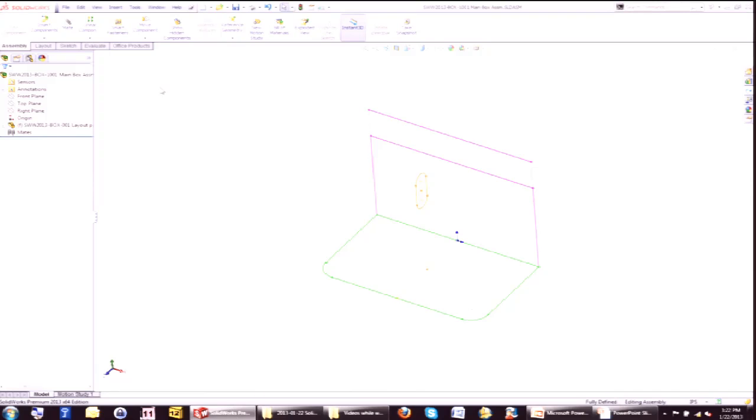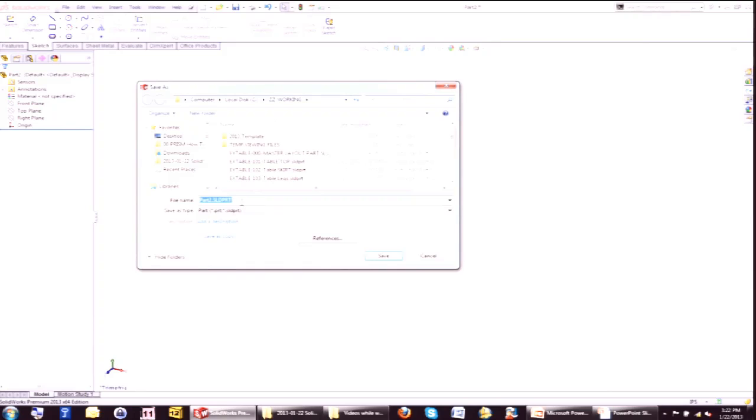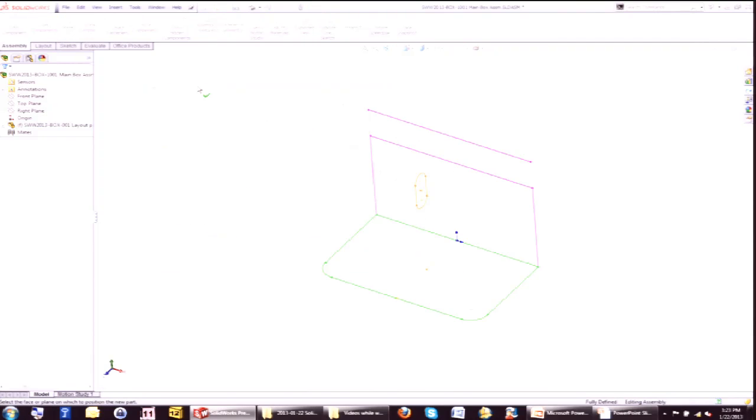So we go into SolidWorks again, and we go Insert, Component, New Part. Okay, it asks us for a name. I've already got that other one that's got that box name in it, so I'll just use that again. SWW box layout part, and this will be 101 box bottom, or 001, or whatever your technique is. Now I get this icon, which is asking me for a plane. So what plane am I going to pick? Front. Excellent. Front. Even though I know I'm going to end up sketching on the top plane, that's okay.